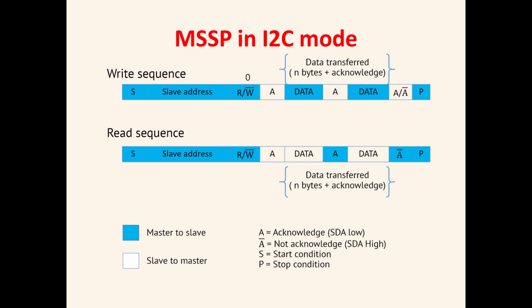Let's assume that we have received acknowledgement from the slave. So now your master is ready to initiate your data. The data bytes will get transferred to that respective slave. As you transfer your first packet of data, your slave again needs to send an acknowledgement to the master as a data acknowledgement.